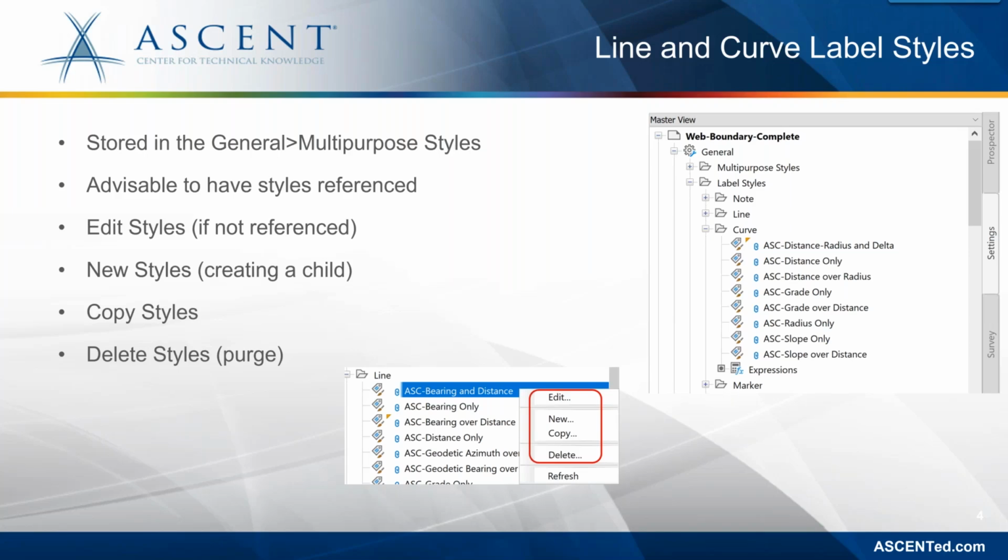Also note that there's a little clip icon next to the label style, and that means that it's referenced from a reference template. I would definitely recommend referencing styles. What that means is that there's a reference template attached to this drawing that controls as many styles as you want.